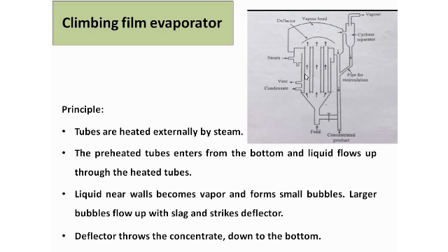So when it passes through this area, the fluid will come in contact with these pipes or tubes which have the hot steam. The heat will be transferred from this hot steam via the wall of the tube to the liquid, and this liquid will get heated. Now this liquid will move up to this area.